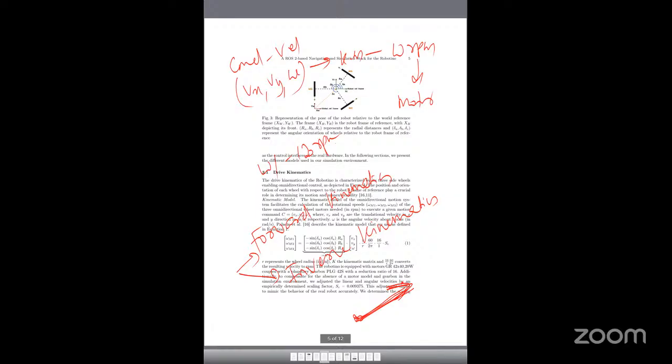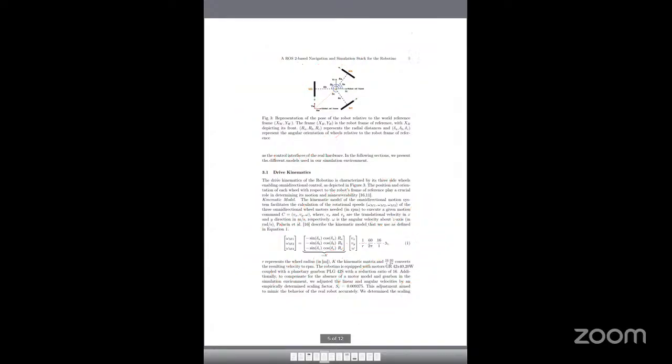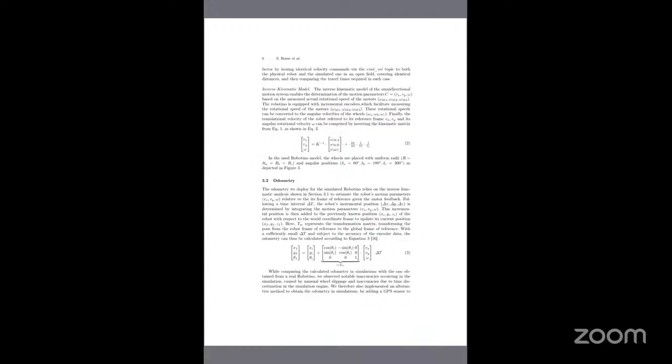So now the robot is moving, right? So the wheel is moving. So the encoder will measure this data. From this we will get the motor speed. Then from there we will get wheel angular velocity, and with inverse kinematics, we will get the robot velocity. Then we have another equation here, equation number 2, write this one.